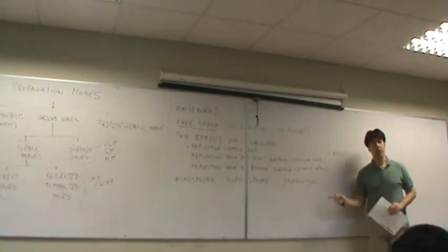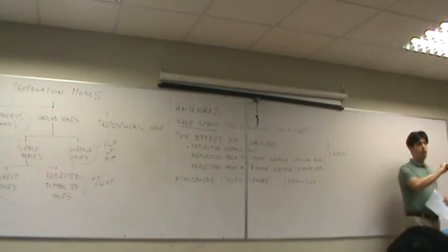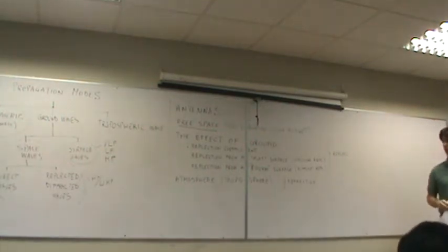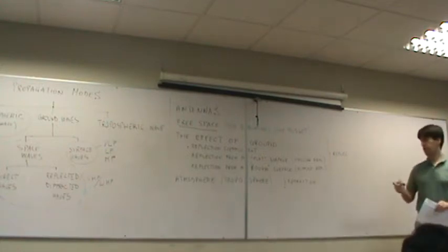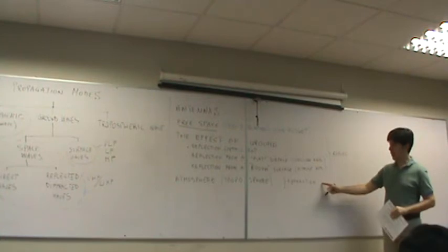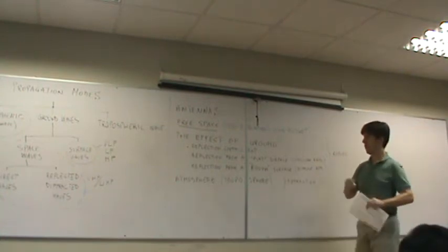And you have to take into account this curvature when you design a radio link whose length is, say, more than 20 or 30 kilometers. So this is the typical problem that you find in microwave links.